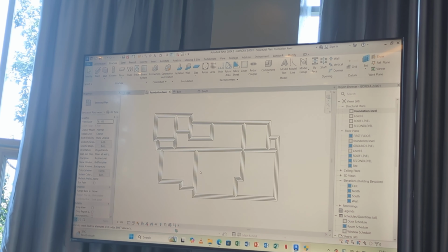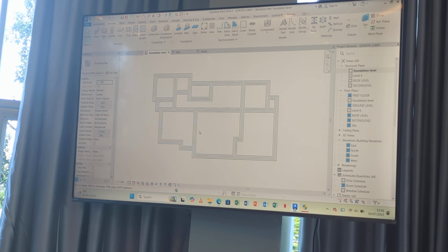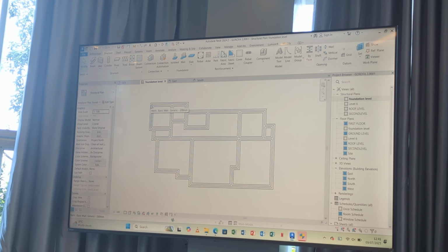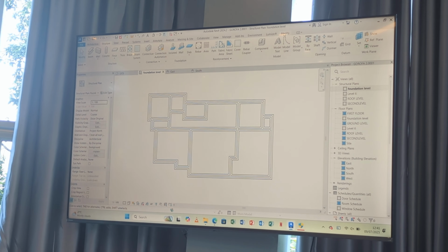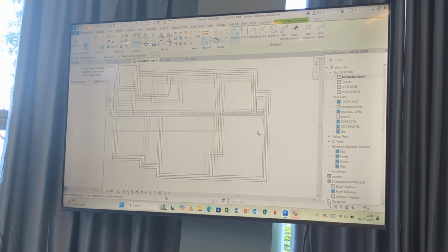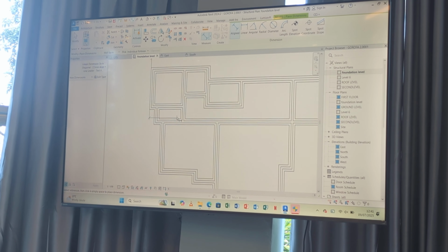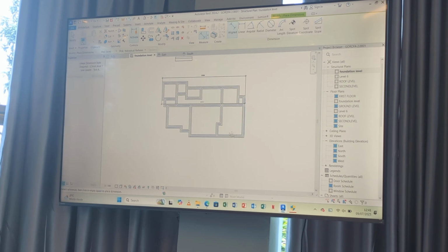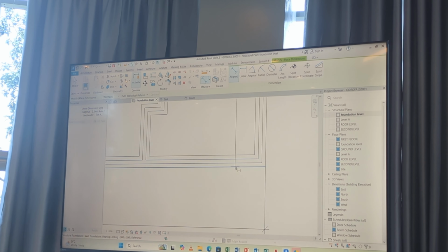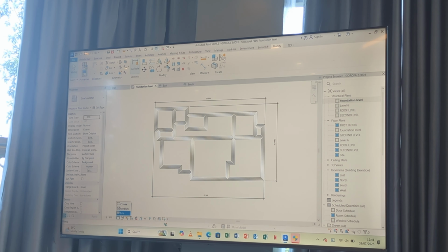Yes. So the same way you did dimensions for every other thing is the same way you do here. You did overall dimensions such that the person who is going to do the digging of this trench knows that I am starting to dig here all the way to there. You get that? Now we are doing detailing for all. Remember we do the overall dimensions on 4 sides? Same here. The farthest point here and the farthest point here. So you can make this fine, make this page fine over here.